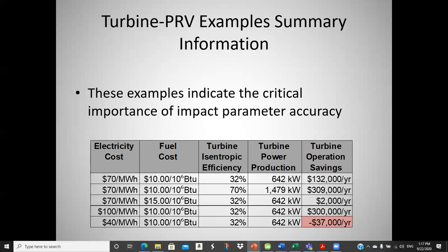Oh gosh, my internet is unstable. It's hard to get a great payback on this stuff, but again, it depends on the spark spread. These days, if I could buy this gas at $3.50, these projects will fly at 7 cent electricity, which is probably about right. So that's probably where this plant would be sitting today: probably between $3 and $3.50 per million on fuel, and probably 6 to 7.5 cents on electricity, depending on where they are.